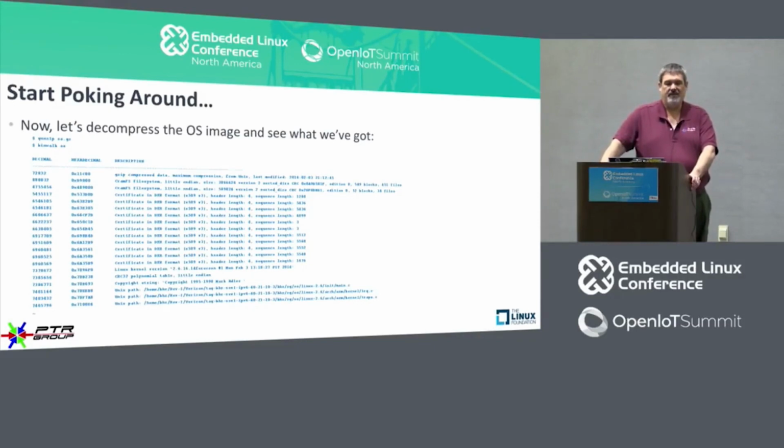Once we did the unzip and then ran Binwalk on that, we found gzip compressed data, 2 CramFS file systems, a whole bunch of security certificates, and CRC polynomials for doing the checks. We found that it was a Linux 2.6.16.14 release of the kernel. When that was made, that dated back to 2014. And we also saw some of the paths for the actual files inside of it.